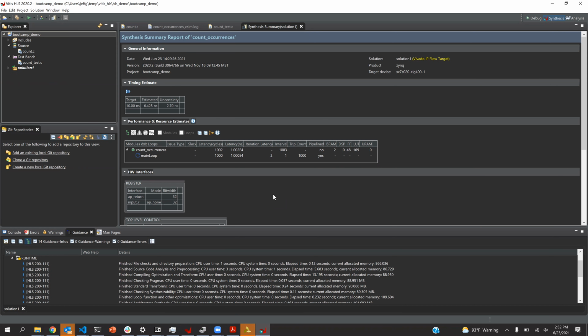Okay, because we have to feed the address into the memory. Remember, this is a big array. We're not adding them up like my earlier example, but we're still doing the same thing. We're going through and looking at all the entries and counting them. Okay, so we have to basically feed an address in, wait for the data to come out the next cycle, and check it. So it takes 2 cycles.